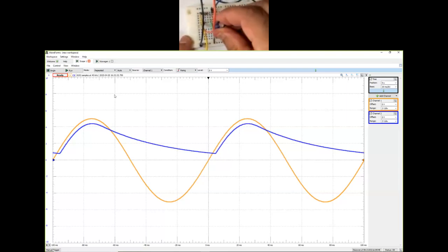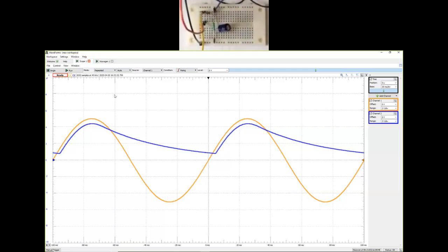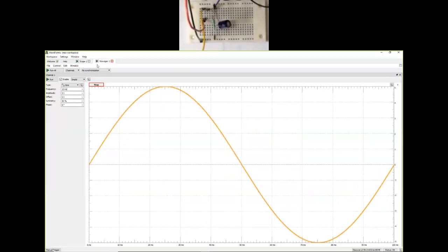So between the same 2 points, it is exactly in parallel with the 10 kilo ohm resistor here, but now it's a bigger capacitor in this case. And just so that we compare consistently, I'm going to run this wavegen at 100 hertz. That's my reference, 100. I'm going up from there, I'm going down from there, but 100 hertz is my baseline. So if I choose 100 hertz, sine wave, sure, everything is okay, let's run it.